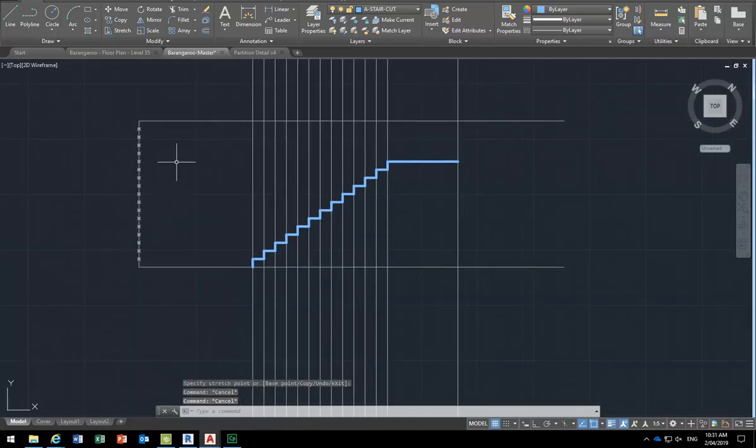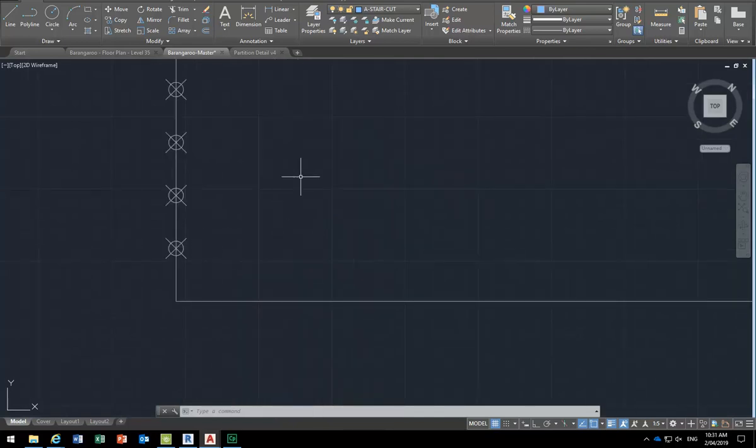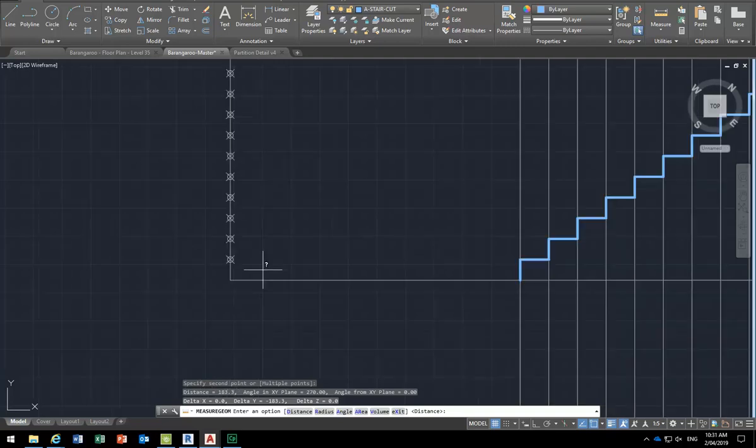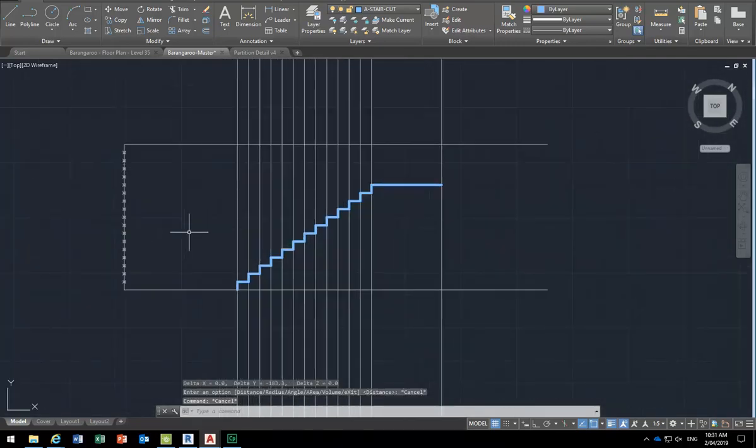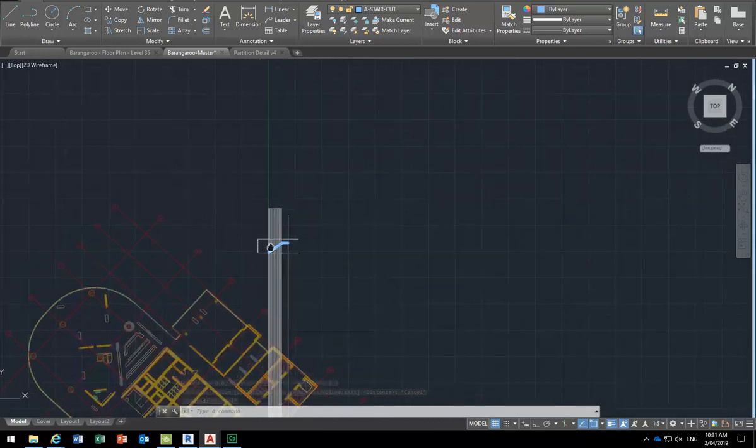But what I should have done before going too far, and I can always come back and you can see how easy it is to do that if I've got to fix it, but I'm going to measure and make sure I got my maths right with that, riser height. So you can see there 183.3, which is perfect. So that's the basic process for setting out stairs, and you can do that from any angle.